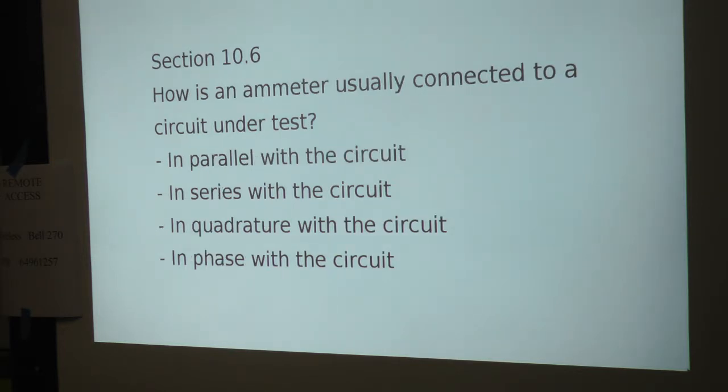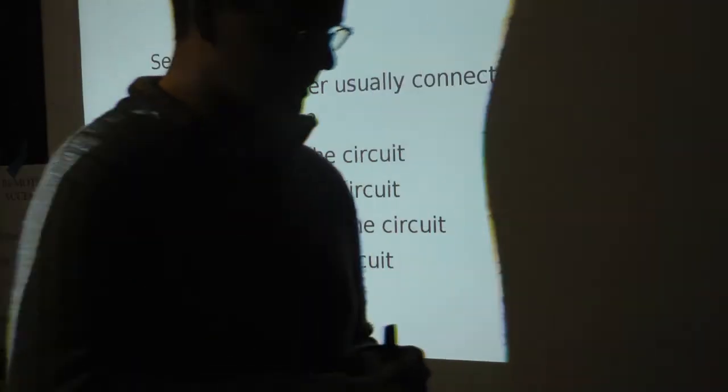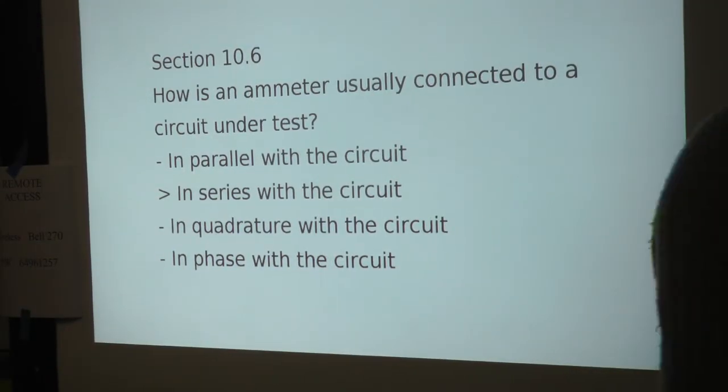So, how is an ammeter usually connected in a circuit under test? It's in series. Well, not exactly. You break the line, put it in the line. So, just a quick drawing, just to recap. We'll go back to our favorite circuit ever, the one resistor, one battery circuit.